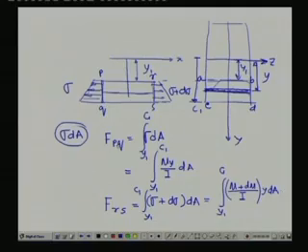So, this is a force onto this segment, this is a force onto this side. Now, of course, the sigma on this side is less than sigma plus d sigma on the other side. So, there will be an imbalance in the force. To balance the force, we understand that a force in this direction at the interface should work, and that we are designating as tau.